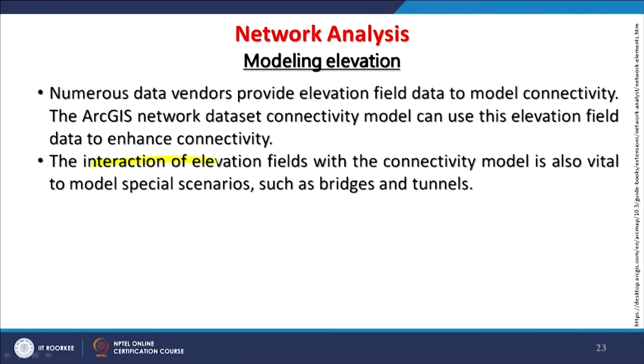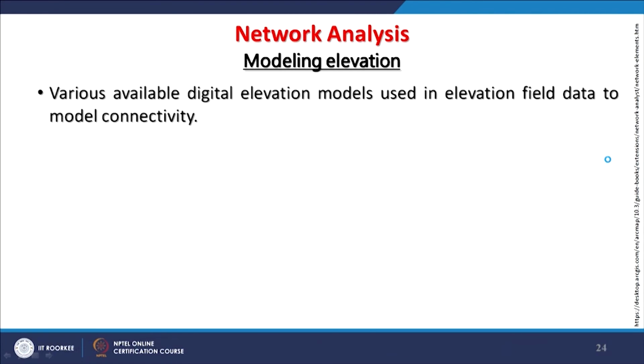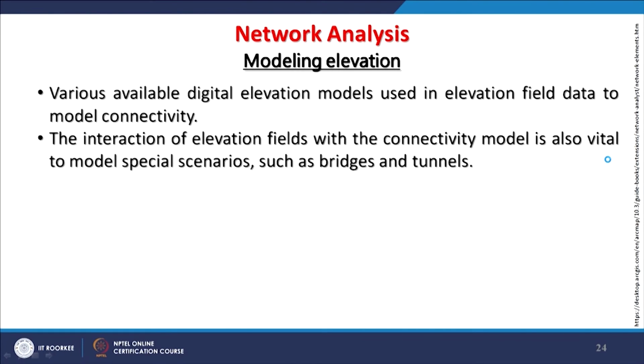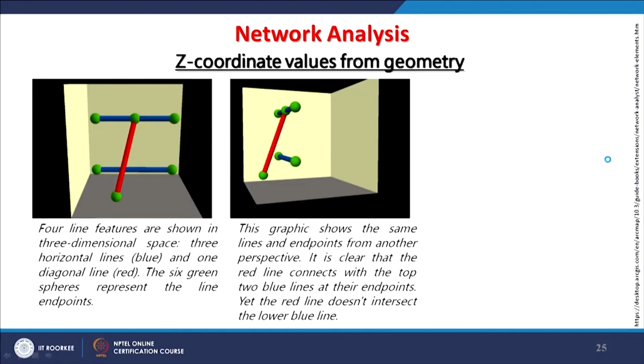So, the interaction of elevation fields with the connectivity model is vital to model spatial scenarios such as bridges or tunnels. Further, various available digital elevation models can be used in elevation field data to model connectivity, but only in case things are moving on the surface. But if you have subsurface conditions like underground metros, then digital elevation models cannot be employed. Then that elevation information has to come from other sources. So, the interaction of elevation fields in our network database with the connectivity model is vital to model these bridges and other